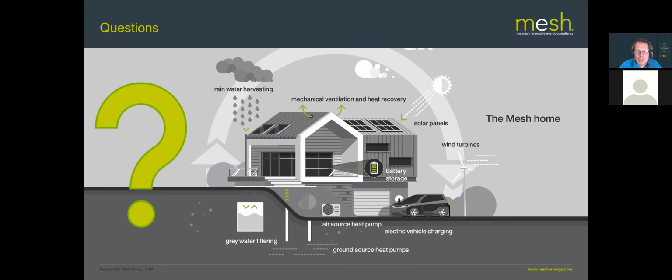So installations that are very close to the sea, where saltwater corrosion can be an issue, then there's certain things you can do to the evaporators in terms of treatments to make sure their life is as good as possible. And of course, choosing a quality product to start with also helps. So looking for good quality compressors, good quality casings, those kind of things.